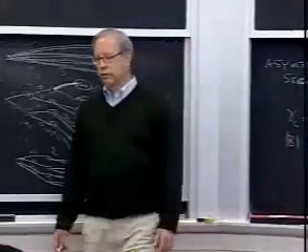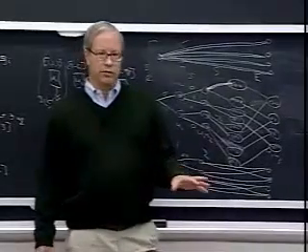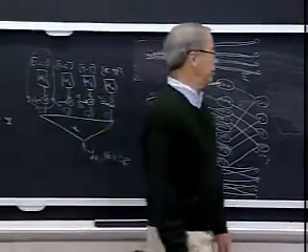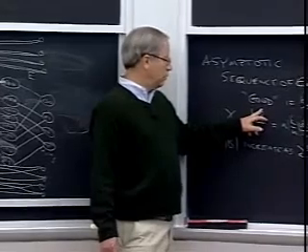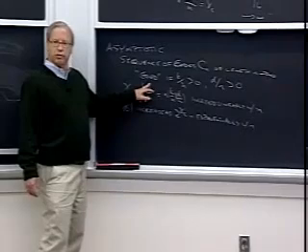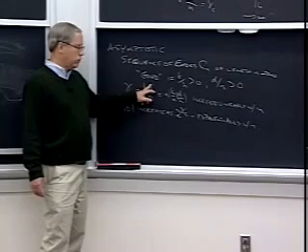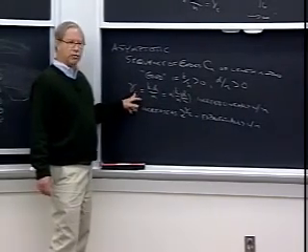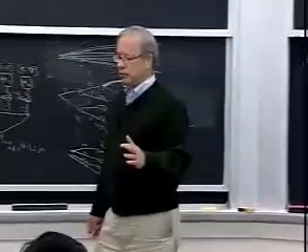At least if we're only interested in a certain error probability, maybe it's 10 to the minus 5, maybe it's 10 to the minus 10, but it's still only a finite error probability. Maybe we don't need the minimum distance to go to infinity. Maybe by sampling codes which are lousy in classical terms, which have poor minimum distance, they'll be lousy in distance terms or in nominal coding gain terms, but they'll be very good from the point of view of complexity. Maybe there's some trade-off here. We know the code is going to have to be long, but maybe it doesn't have to have large distance.